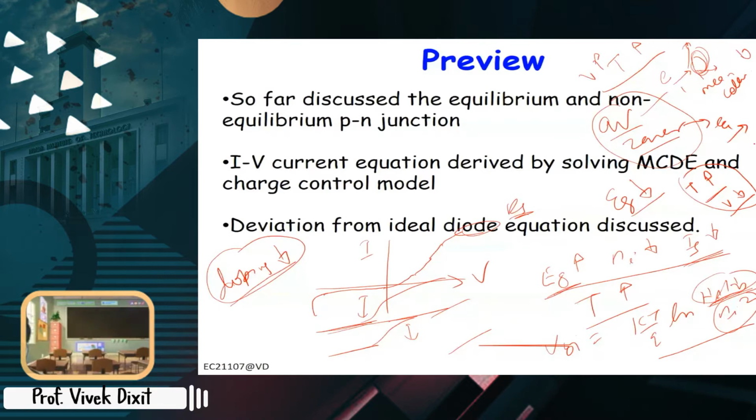So that is the way to find out whether this breakdown is avalanche breakdown or Zener breakdown. Avalanche breakdown has a positive temperature coefficient. Zener breakdown has a negative temperature coefficient. Okay, when I'm saying the voltage is increasing or decreasing, it means the magnitude of the voltage, because sometimes we say this is basically negative voltage, right? So don't confuse. It's the magnitude of the breakdown voltage.